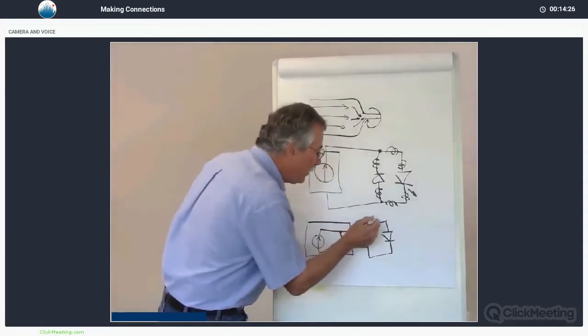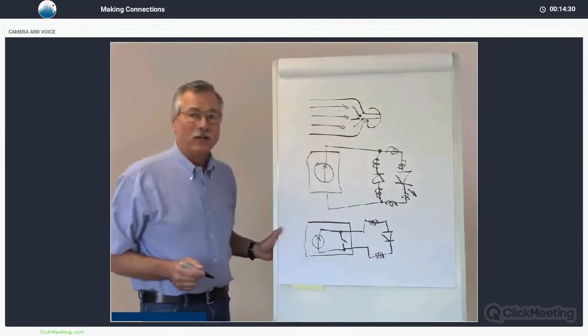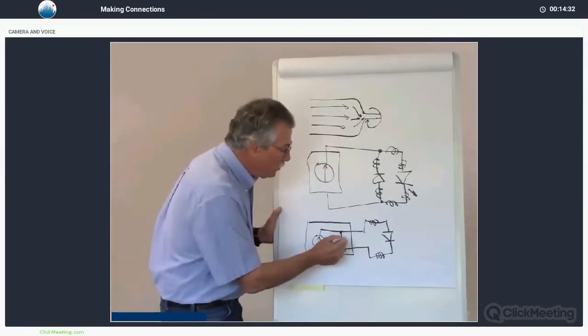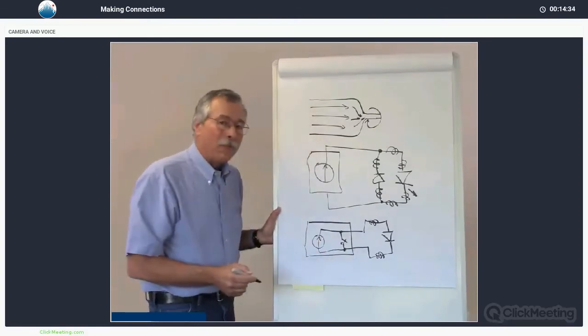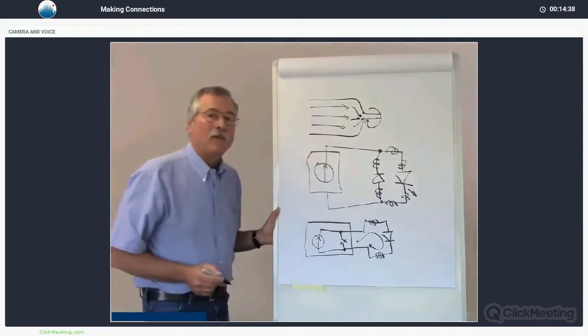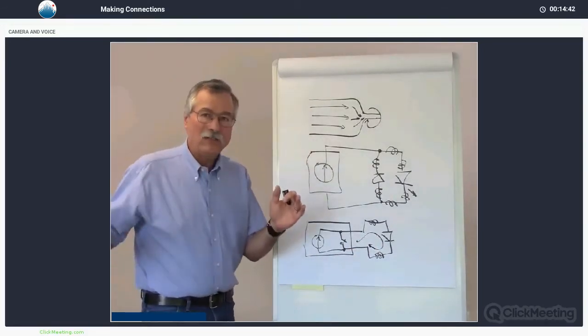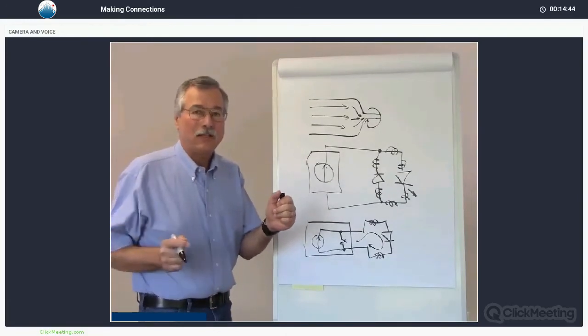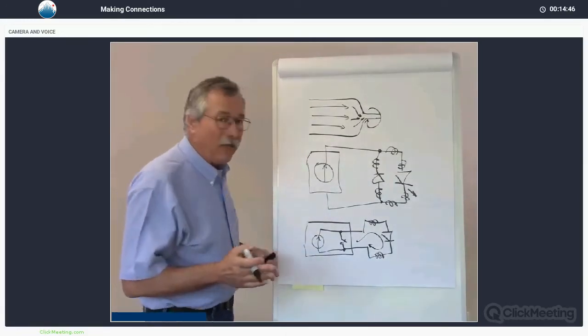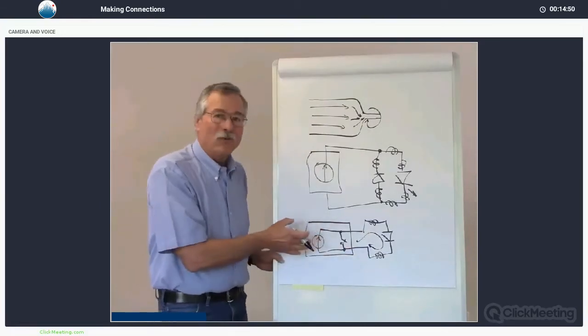Well, we have inductance, as you know, throughout this wiring. So when we close the switch, the inductance is going to want to keep this current flowing. That can result in a pulse that has a very long tail, and we'll be showing you examples of that later on. In any case, as you can see, the inductance is the bad guy here. Inductance isn't always bad.